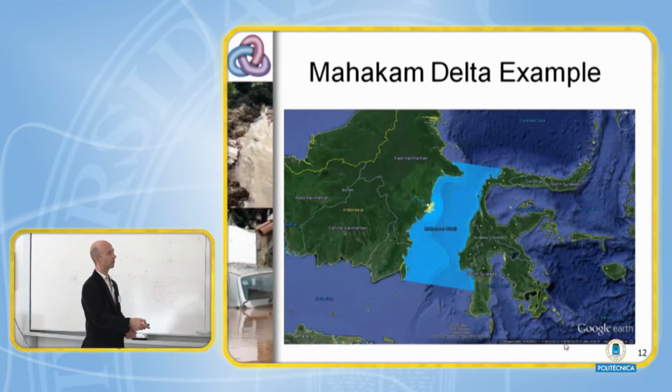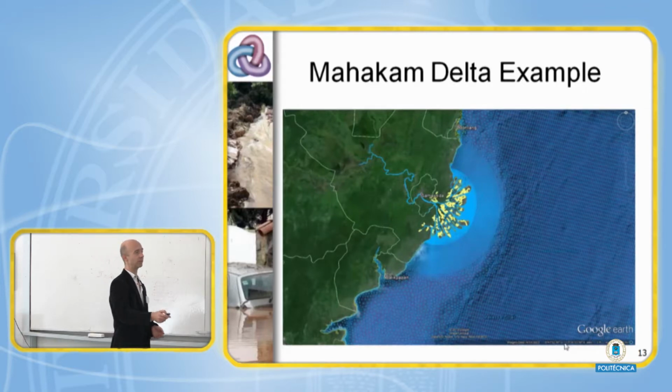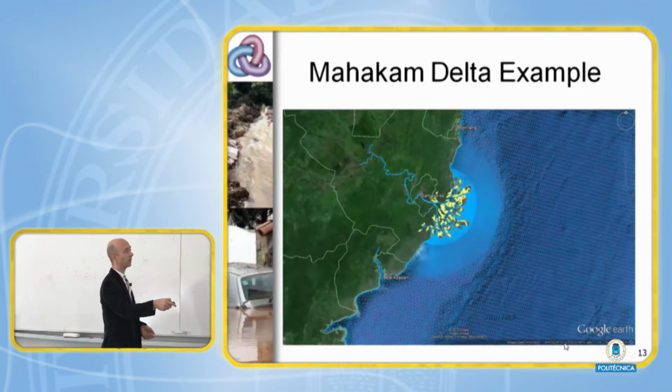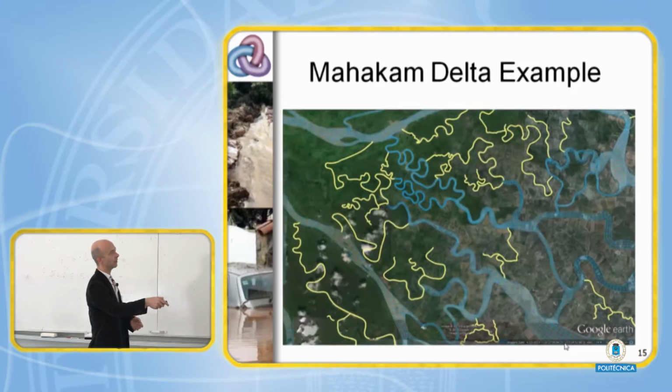So we start with a grid covering a whole part of the ocean, and then for that part you can use a Cartesian, more or less Cartesian mesh, and then if you zoom in you go to a curvilinear mesh. We fix things in between, the transitions, with triangles, and then if you zoom in you get meshes that follow the individual channels, with some triangles to merge the channels together.